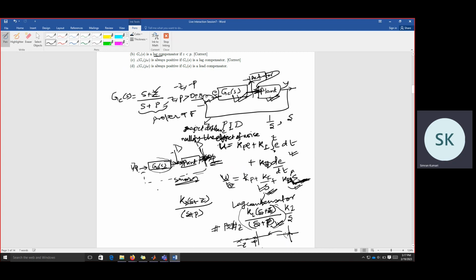These are also some of the properties achieved via feedback control. So in that case, when we are using this derivative term, if this is the controller part, and the error signal has some high frequency component, so suppose this error is varying like this, and now if it has some disturbance, it is varying like this.